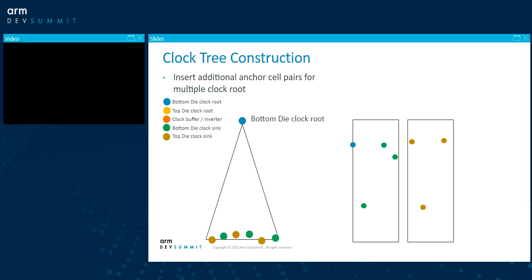So regarding the clock tree construction, the primary concern on 3D clock tree is OCV, as always OCV. The on-chip variation is pretty restricted, notably in this kind of CPU design. It's pretty much restricted by our CPU microarchitecture. Typically, we have sequential clock gating to save power and to minimize the OCV in a 2D context. So we have 3 levels of clock gating: architectural, regional, and the synthesizable local clock gating. So it's really hard for us to use a traditional mindset to implement the 3D clock tree to mitigate the OCV. From here, on the left side, you can see the whole clock route across the tiers. So it's shown in 2D.